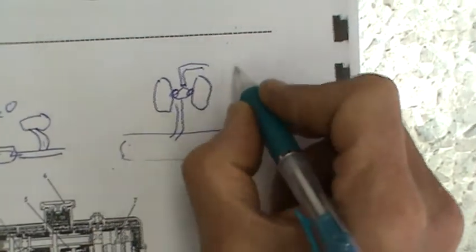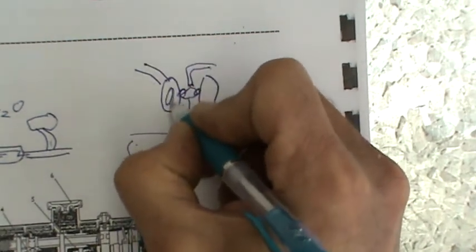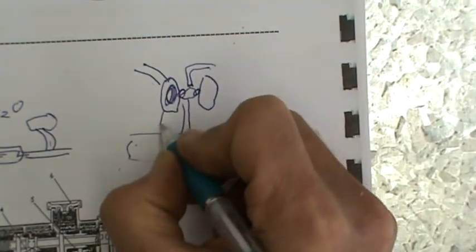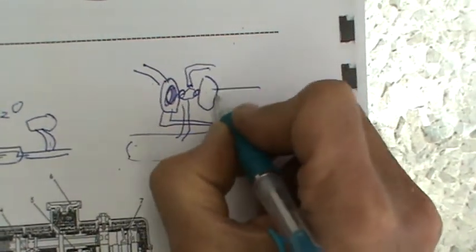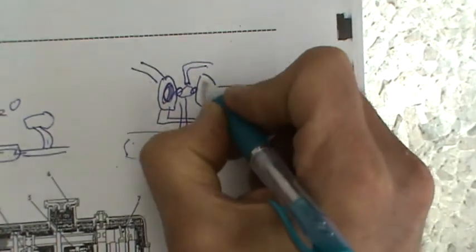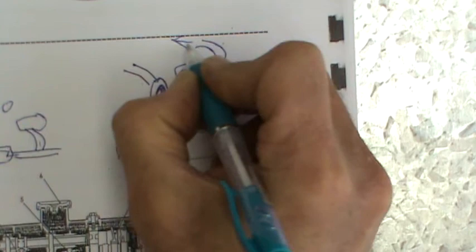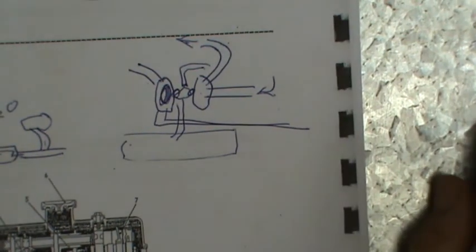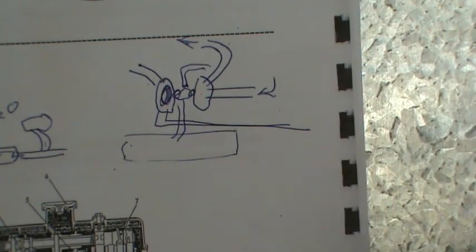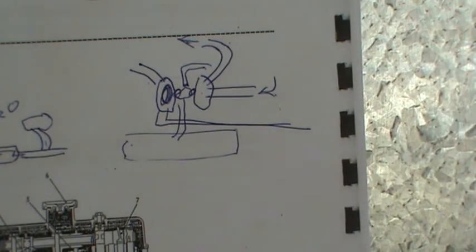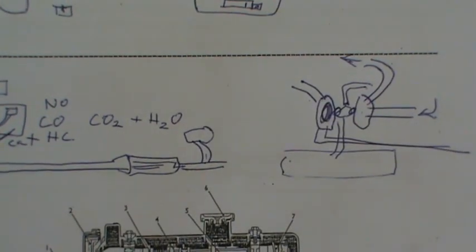What it does is it has the exhaust feeding into one side of it, which spools it up, and then the exhaust goes out, and the other side has the air intake from the air filter, and that's pushing large volumes of air up to your manifold. So that's another system you might find on your exhaust. Alright, so that's probably enough for our 7 systems of a vehicle engine.